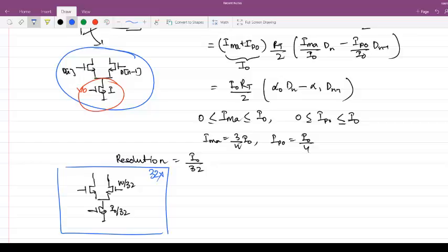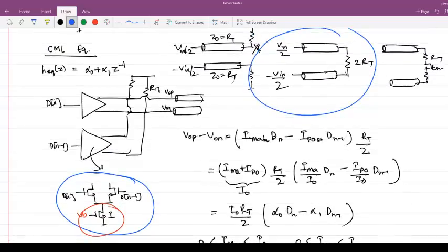Like I can choose 16 here, 16 there, or in this manner. Now if you look, this is the case only with one post cursor and one main cursor. As your number of taps increases, you will keep on increasing this 32x if you want that resolution with full freedom, right? What will that do? That is going to increase the capacitance looking at this node.